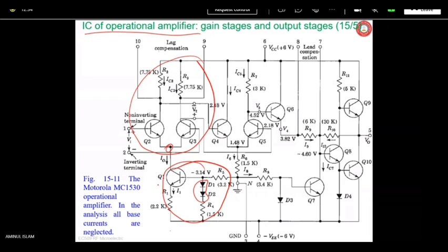The rest of the op-amp may have other BJTs, but the first stage you can replace with FET based so that its input resistance is high. We know that, and there will be no problem. Valuable signal from the source may not be lost while it is being applied to the input of the differential amplifier.